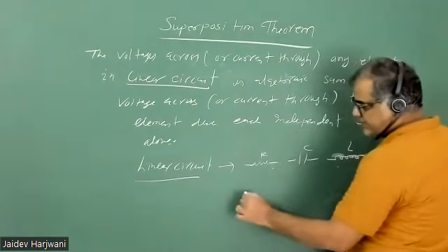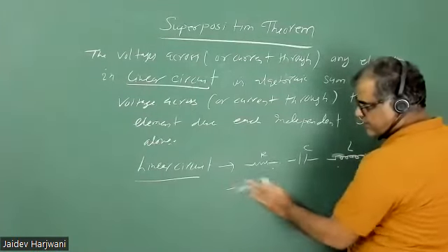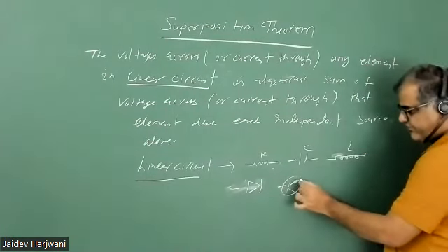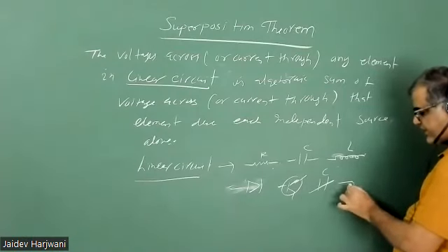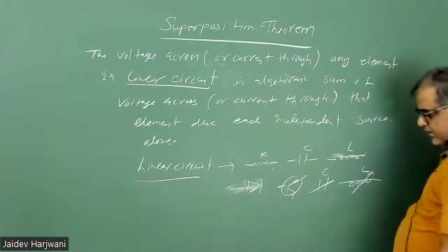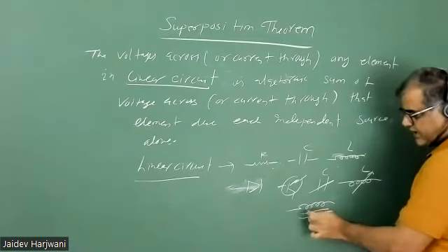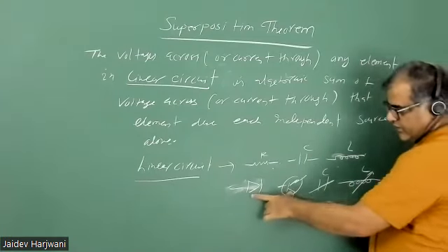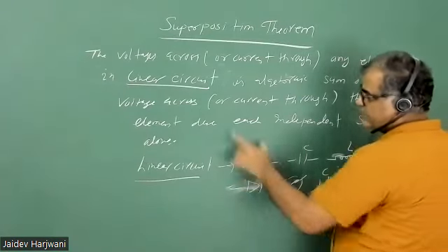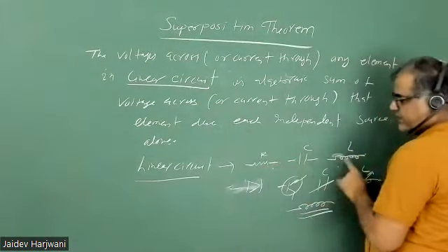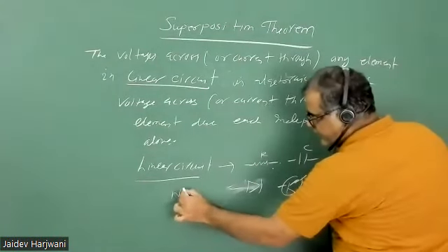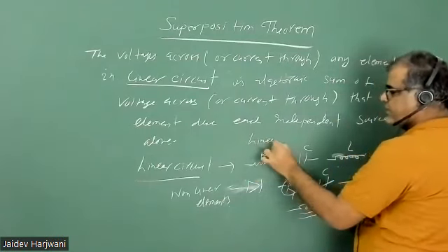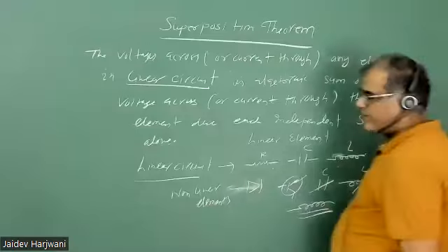But if in the circuit there is a diode, which has a variable resistance, or a transistor, or a variable capacitor, or an inductor L which is variable, or an inductor wound on an iron core, then this L value will not be fixed. Similarly, if C is variable, then the C value will not be fixed. These are all non-linear devices, non-linear components. So you can apply the superposition principle when you have only linear elements R, C, L. These are linear, and these all are non-linear elements. So your elements should be linear, then only you can apply the superposition principle.